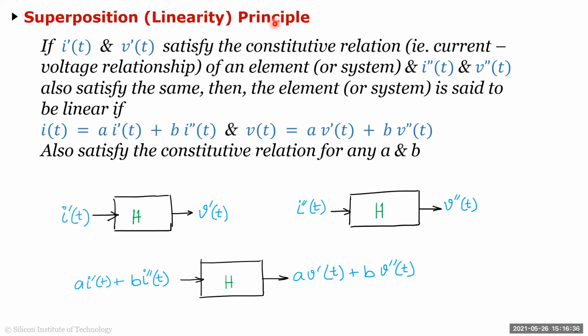The capacitance VI characteristics at the time after breakdown, it will start from some positive value. So it is not passing through the zero line. That's why I think that it is non-linear. Yeah, no, so forget breakdown. Breakdown is like talking about second order effects, but just a pure capacitor, right? So you're saying the VI relation doesn't pass through zero, and that's why it is nonlinear. Okay, and that's the general sort of intuition why people think it's nonlinear.